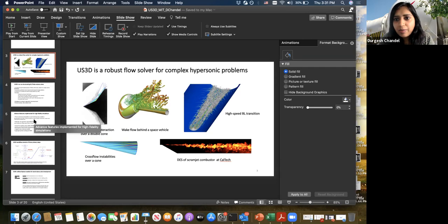And even for my shock tube problem, the code by default did not have the capability to solve it accurately. For example, the code uses an iterative implicit algorithm, where within an implicit time step you perform sub-iterations to compute the Jacobian. Depending on how many of those sub-iterations you perform, the accuracy of the linear system is dependent on that maximum number of sub-iterations.